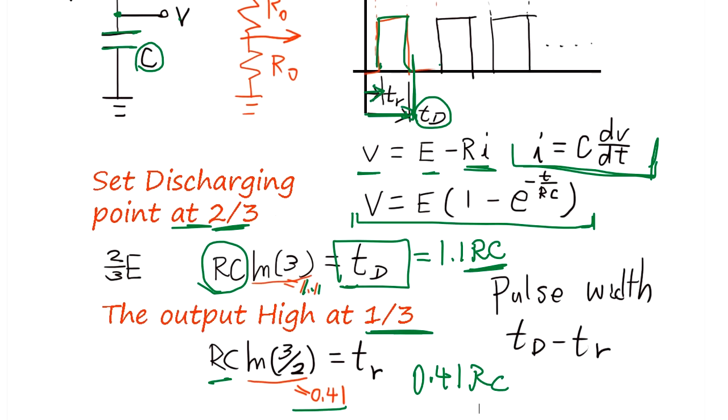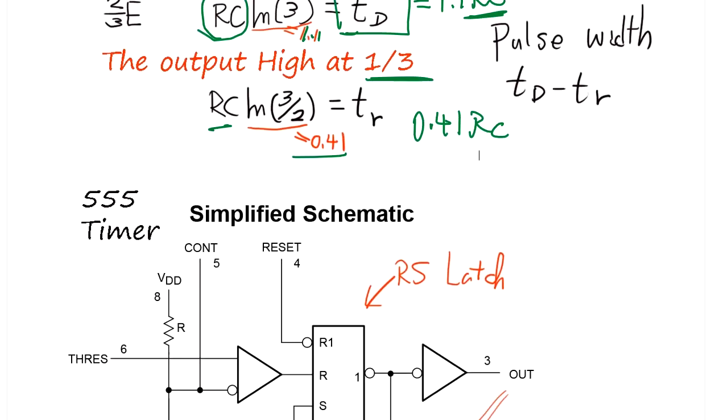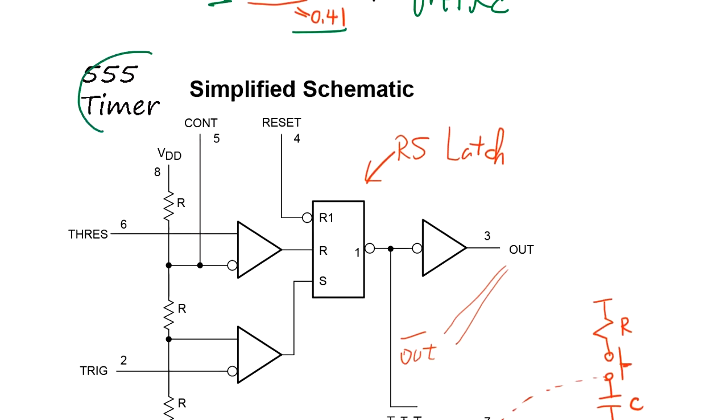It's already made. That's the IC chip 555 timer. The 555 timer is made of comparators. Internally, the power to ground is divided into 3 voltages, and this 2/3 is used by a comparator. This is the threshold signal you set. Then we can give a signal R.